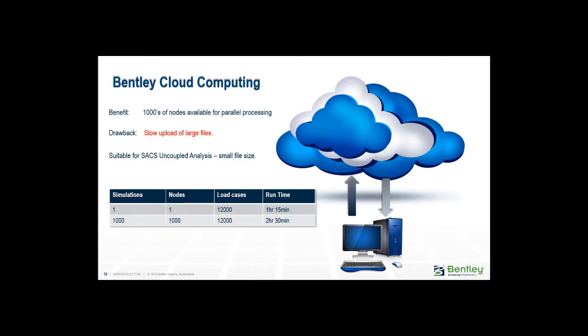Now, Bentley's cloud computing: the benefit here is the cloud has thousands of nodes available for parallel processing, so it can conduct analysis really, really quickly. The drawback is it's a slow upload of large files, so the results files from GH-Bladed are not really recommended for cloud computing. It's suitable for SACS uncoupled analysis because the upload is small files.